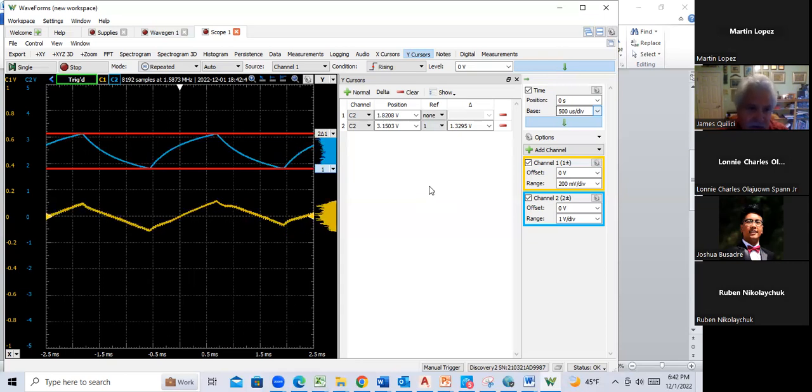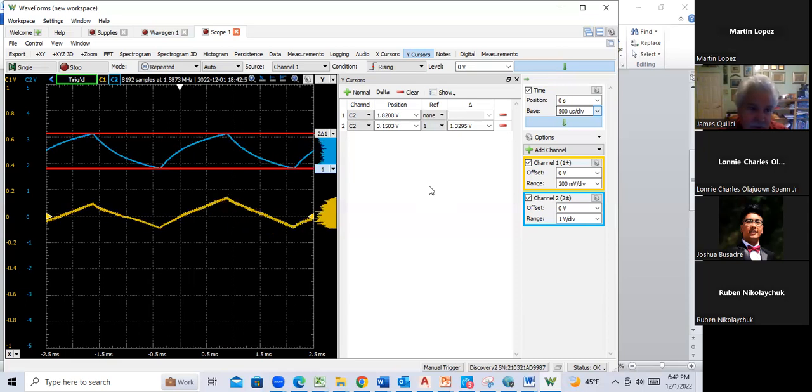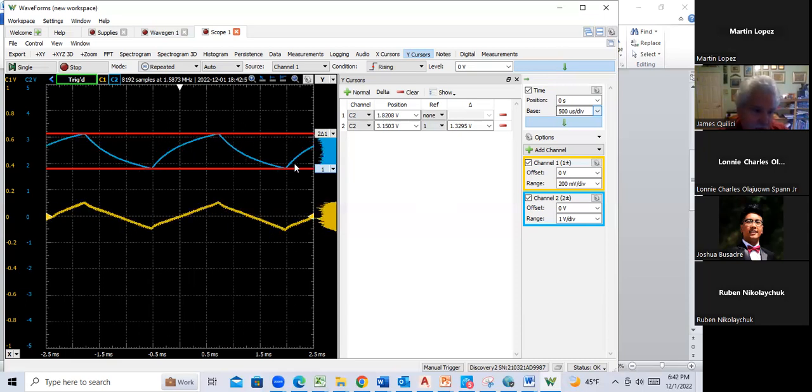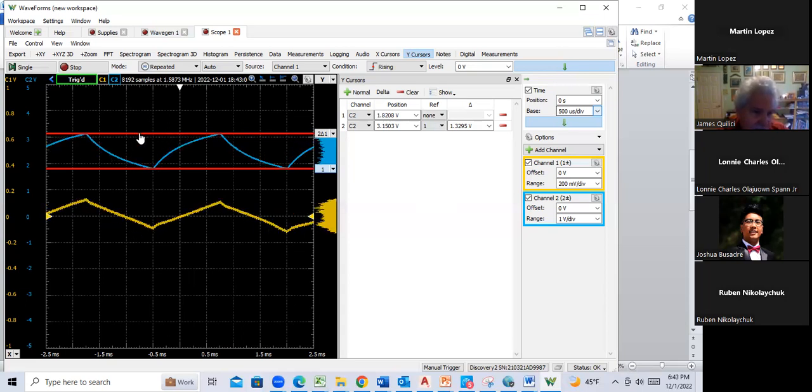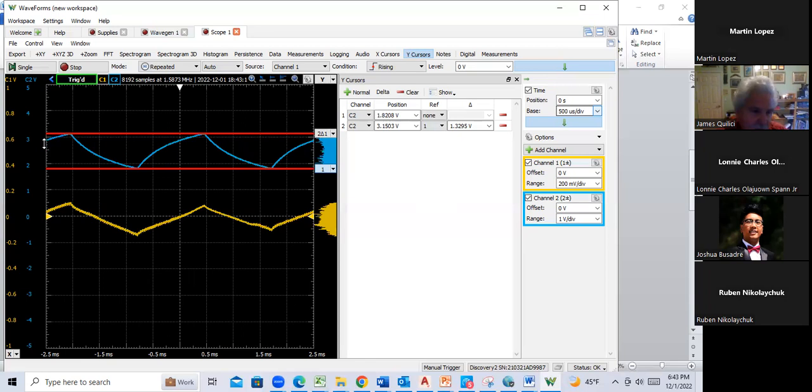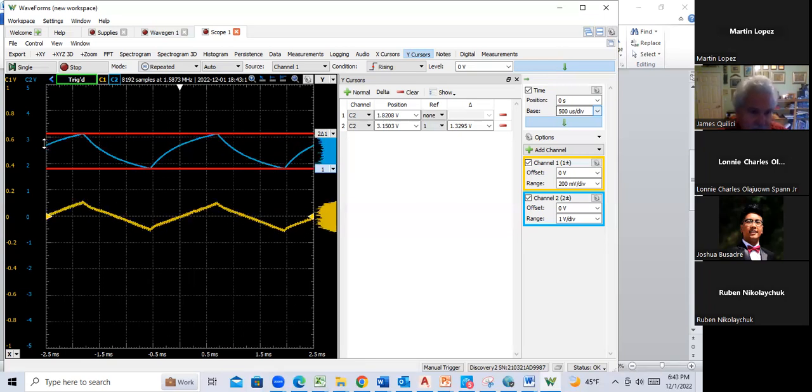And if you do that, also send a picture of your schematic and what's going on in your waveform too. Again, what I'm looking for on mine is ideally this thing oscillating right around a DC offset of either 2.5 or 3 volts. That'll give you the most dynamic range. That's basically your collector voltage there. And then your base should probably be somewhere on the order of 1.3 volts to 1.6 volts for this thing to operate well.